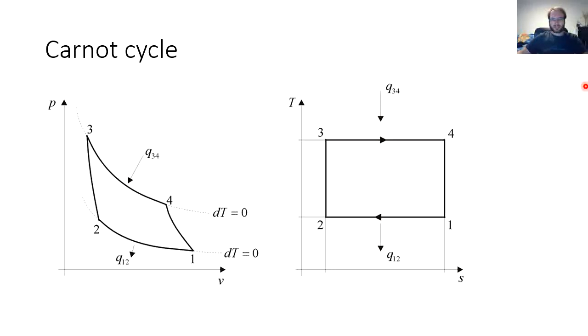The first thermodynamic cycle which we will look at is the Carnot cycle, because it's the specific cycle, or specific system, that stands out because of providing the theoretical limits of the efficiency between two temperature levels. The Carnot cycle is shown here on these two diagrams: PV, pressure volume, and TS, temperature entropy. Now let's go through the specific thermodynamic processes in the cycle.